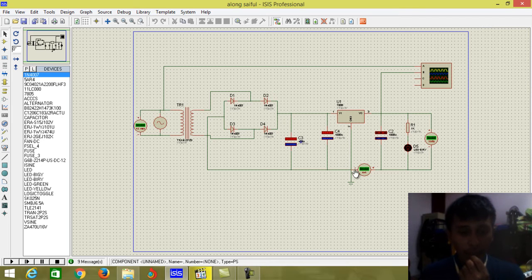Before that, I should explain there are 2 types of voltage regulator, linear and switching. The voltage regulator IC that I use is LM7805. It converts the DC voltage into 5 volt DC. From VI to VR, it must pass through the 7805 internally and to VO. The output must be 5 volt.